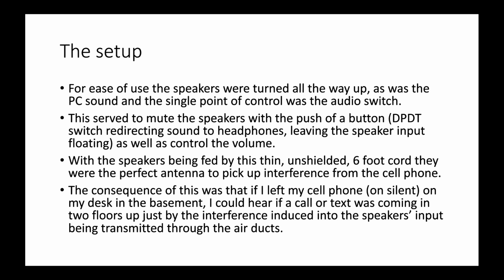And so I ran everything at maximum volume all the time, fully amplified, with the exception of this tiny little media hub. It has a button on it for switching between speakers and headphones. Inside of it, all it does is it switches the left and right channels, not even the ground, but switches the left and right channels from the speakers to the left and right channels for the headphones. And it doesn't connect anything to either of them when they're not in use. So it leaves them nice and floating and susceptible to interference as big, long transmission lines.